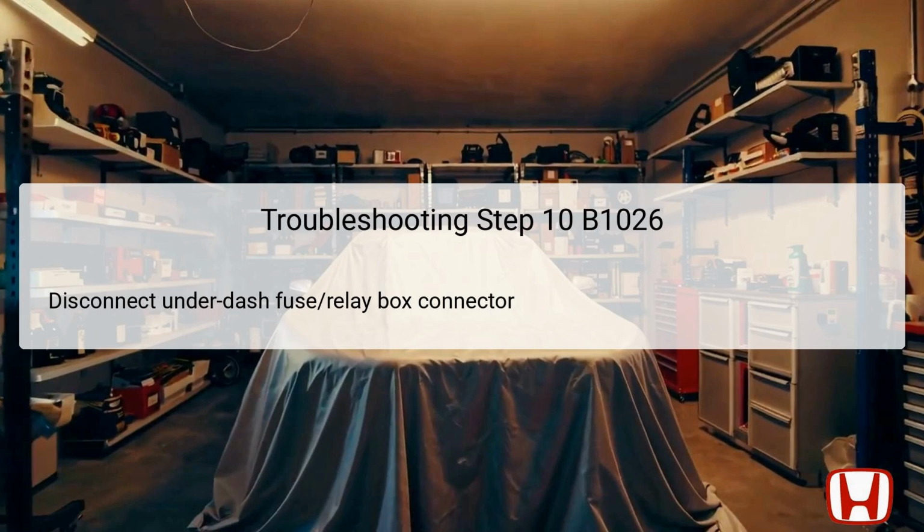Evaluating the wiring between the connector and the power window switch in isolation will offer clarity regarding where the fault might lie. It emphasizes the importance of isolating sections of the circuit to avoid confusion when measuring continuity.